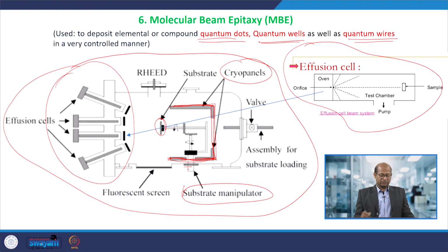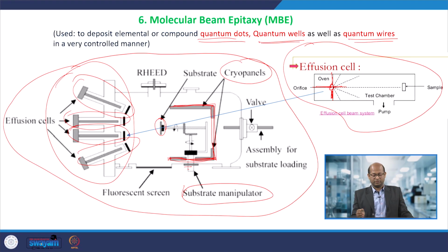In effusion cells, this is one particular metal, this is another, effusion cell 2, 3, 4, many types we can use. And in the effusion cell there is a closed barrier with a small pore or orifice through which whatever materials we are going to diffuse pass into this particular chamber. So, that cell is important. Here it would be a target like this, means if, let us say, nickel is present, then nickel would be deposited over the surface.